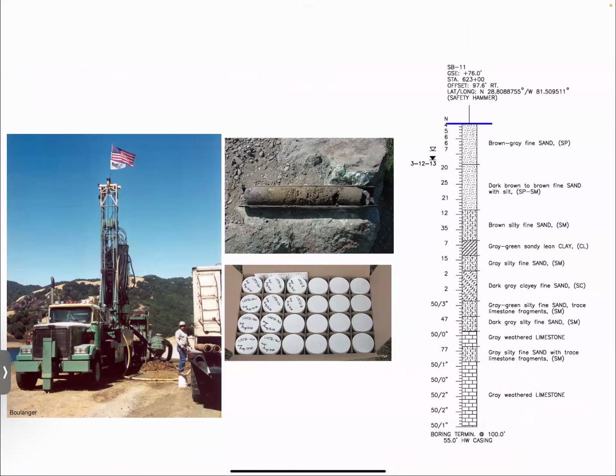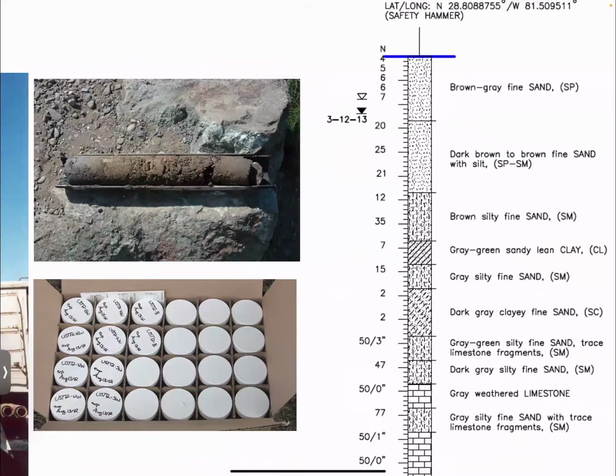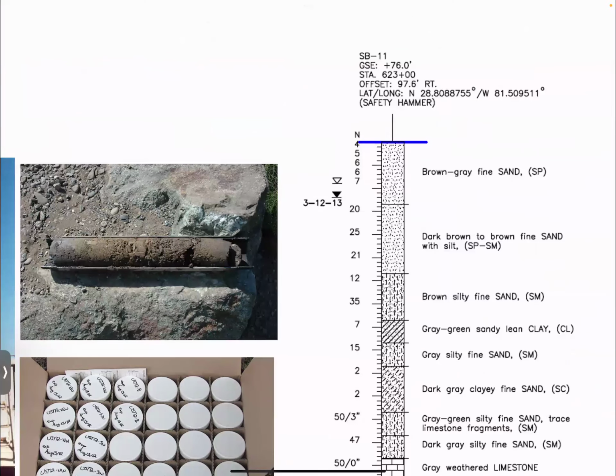So this is part of the standard penetration test. And if you've ever looked at geotech reports, this is what you'll see right there where we see N. So what we do is we do this with depth. One of the limitations is we can only find an N value every 2.5 feet in depth, simply because of how we calculate it, right?